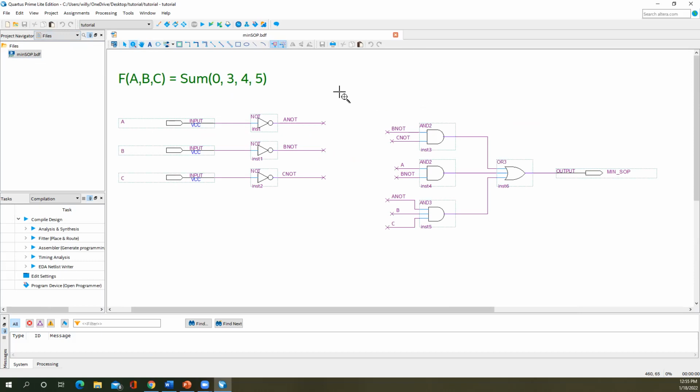All right. So this corresponds then to the circuit you are given, right? Obviously, I'm using a different circuit. What I've done is I've used the text tool here to type in the circuit I'm working with. It's a good reminder for me to let me know where the 1s and 0s are when I test this. I'll show you how to use the text tool when we create our own schematic. We've got our input pins here. We've got our signals named. I'll show you how to name these wires as well. But this actually then implements that equation.